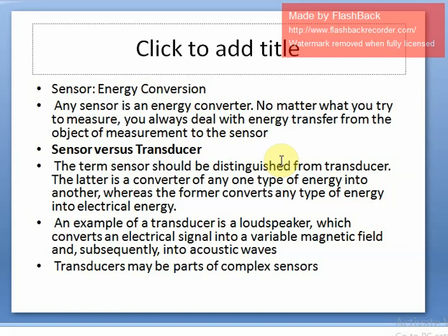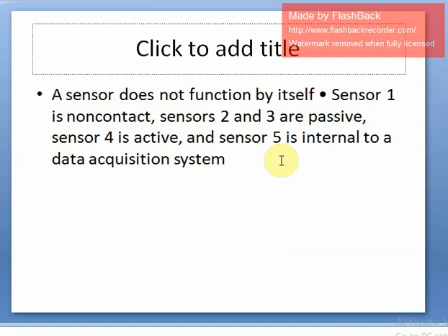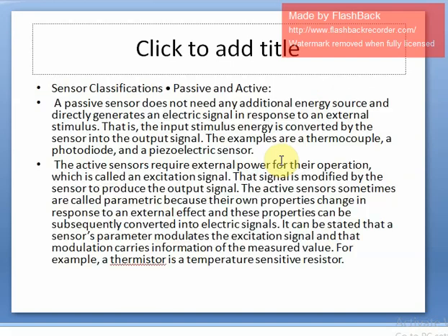Hope everyone understands sensors versus transducer, right? The sensors have different features. They are sensitive to the physical property that is being measured, and only to that measured property. So basically a temperature sensor can sense only the ambient temperature of the room. It is insensitive to other changes, maybe changes in the atmospheric pressure or changes in the lighting condition of that room, right?